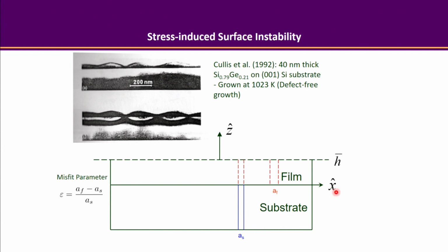Because we just start to deposit the silicon germanium atoms on the substrate, during deposition, there will be a very nice coherent surface occurring on the film substrate surface. So we are expecting to see the silicon germanium align well near the substrate. In a sense, the film's lattice spacing is forced to be constrained, right?